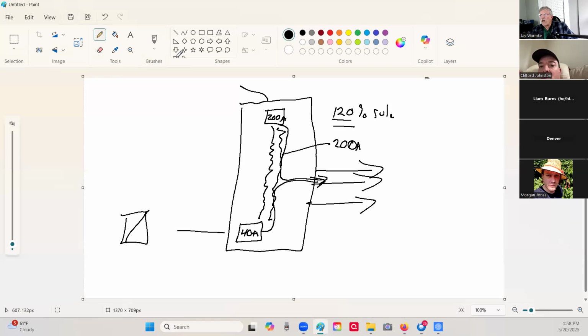And when you're installing solar into a circuit breaker box, this would be known as a load side connection. You want to make sure that you go as far away from the main as possible. That's not always a problem because usually the open spots are down at the bottom, since people just fill in from the top. So you just go to the very bottom and you go into those locations.